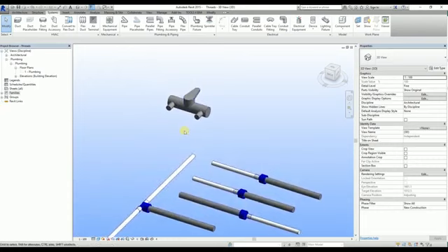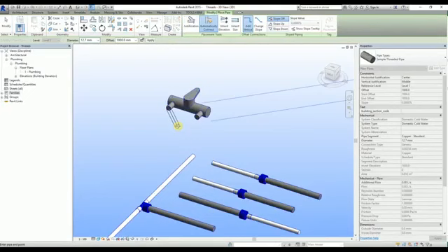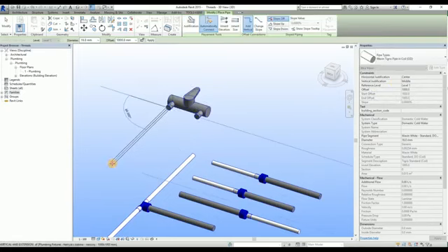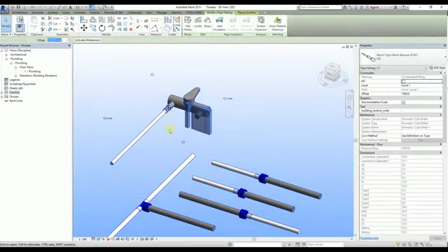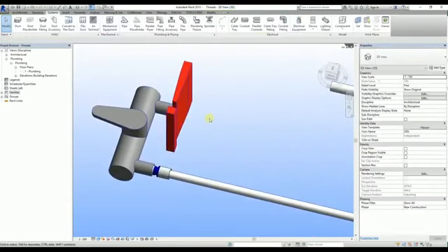When we are working with fixtures, Wavin threaded fittings work in the same way. The fixture has 1/2 inch connectors, which are shown as 12.7 mm. Let's start to draw a Tigris pipe out of one of its connectors. We see the red exclamation mark again, which we need to click and change the fitting into a threaded one.